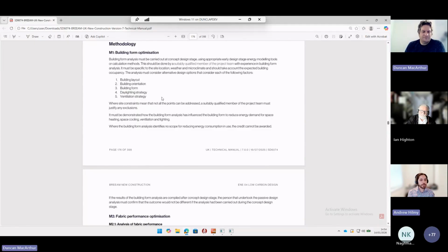Shade positions as well, the position of shades, like overhangs, fins, number of fins. And building orientation, that's an example in the manual where we rotate the building to try and minimize the demand, heating and cooling demand. So there's scope for solving these types of problems as well.